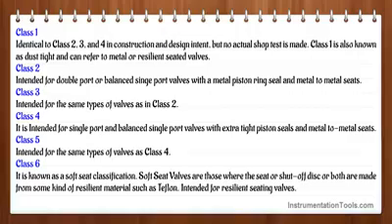Class 6 is known as a soft seat classification. Soft seat valves are those where the seat or shut-off disc or both are made from some kind of resilient material, such as Teflon. Intended for resilient seating valves.